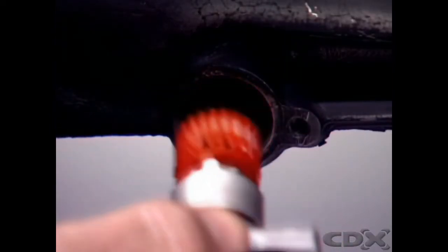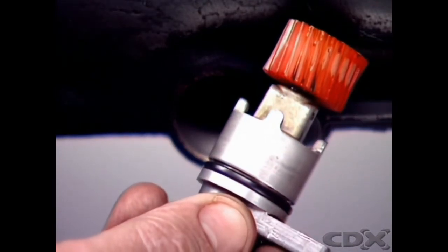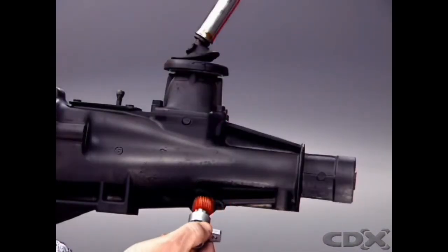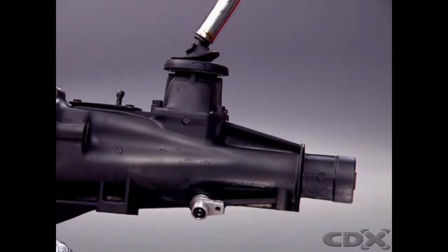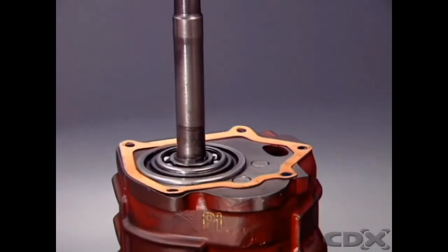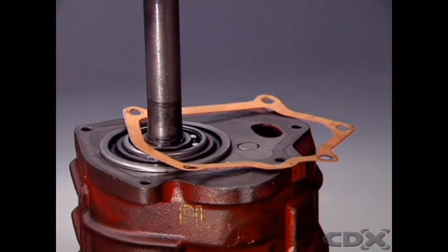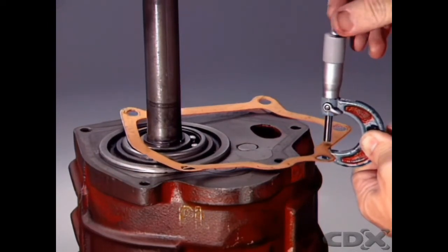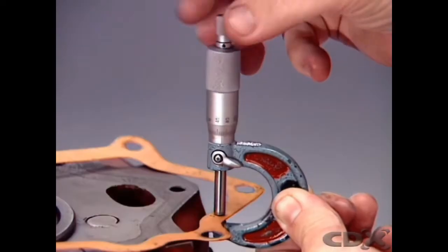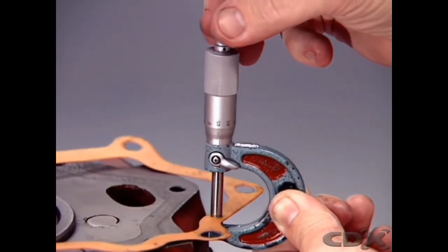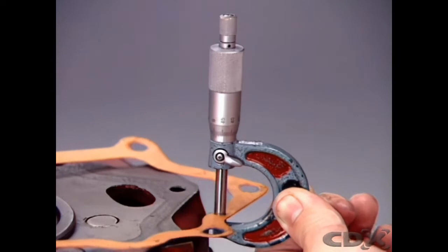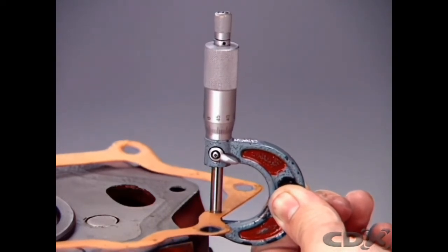O-ring type seals are mostly used for static locations, such as the speedometer drive gear housing, while gaskets are used to seal the mating surfaces between the casing and retaining plates or housings. In some cases, the gaskets may be used as selective thickness shims or spacers, in addition to their sealing function.